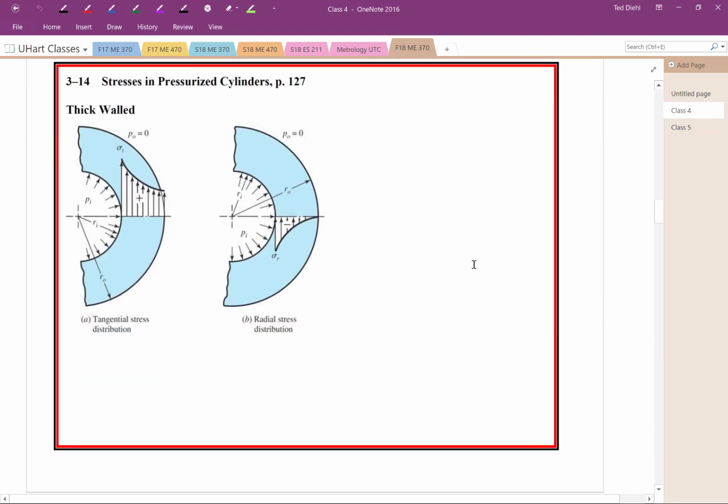Now, I'm going to go ahead and try to organize this. I recall people having some confusion, so I'll try to clear that up. First of all, there are 3 kinds of stresses in pressure vessels. I'm sorry, I said pressures and I meant stresses. And so they are tangential, which I'll just write as tang, aka hoop. This is probably the most important one.